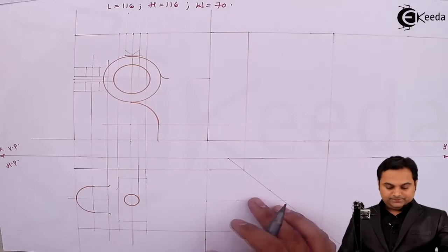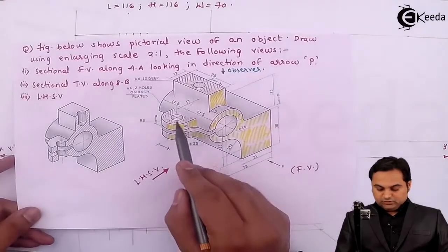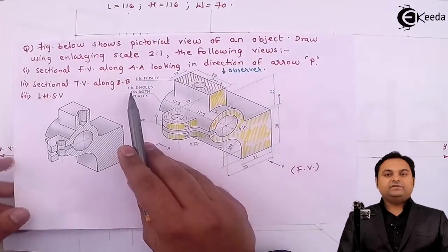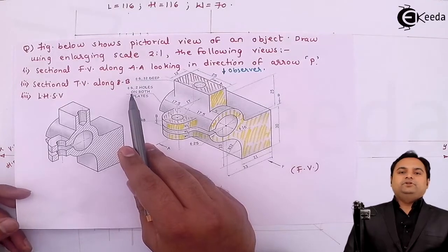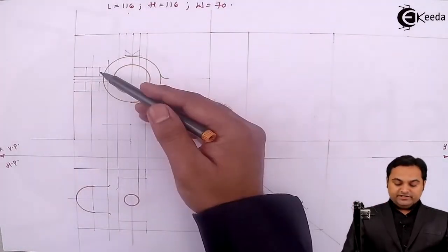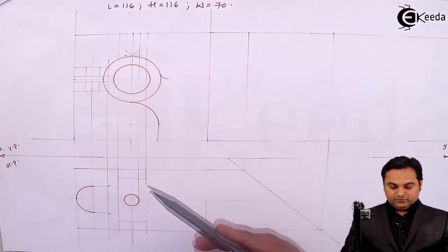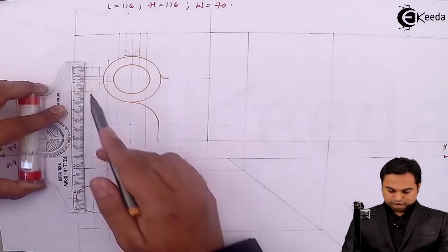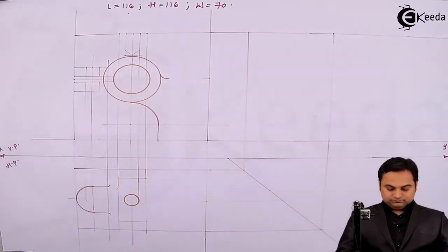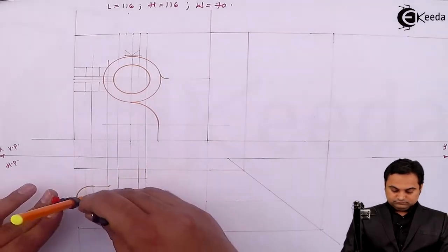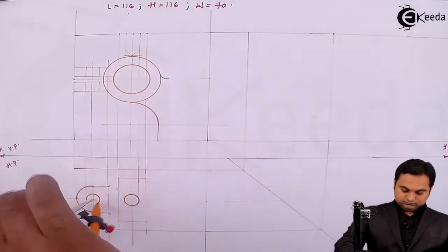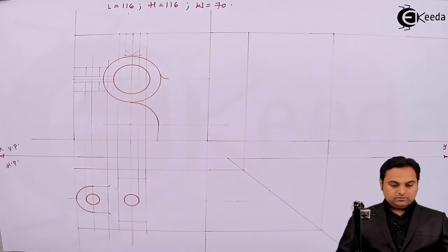Then after that, there is a hole inside this plate of diameter 6. It means that will be of diameter 12 for us. Its radius is there already in the front view. I'll project it down, getting this circle.